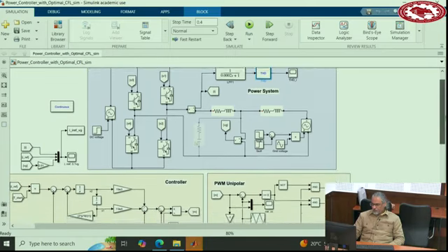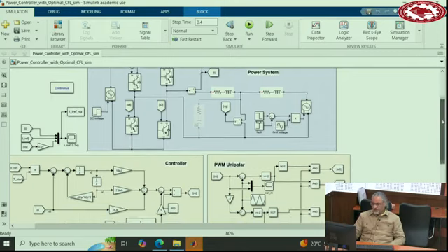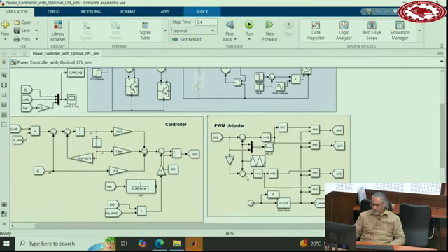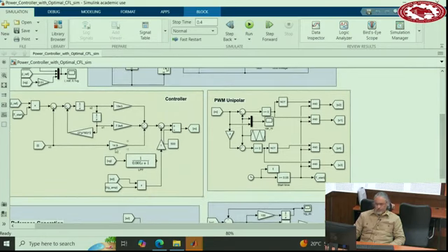Okay, so here is the AC grid, and here I applied the voltage drop in the AC grid and those things, so we use a controllable voltage source. This part is the PWM, it's a unipolar PWM. This is the controller, which the reference comes into. There is a T start, because we want to wait a little bit and then start. So you need to define a start. So the start at that point multiplies in this one, and then minus the current.